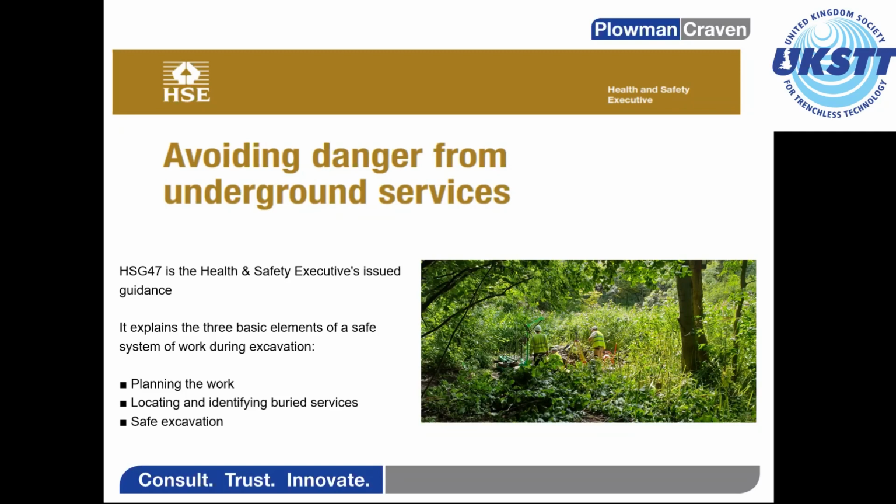This promotes the need to carry out underground utility surveys across all work sites, implementing PAS 128, which is going to improve the level of detail. It deals principally with the risk to health and safety rather than damage to services. However, precautions taken which reduce risks to people's health and safety will generally also reduce the risk of damage to services, which can directly or indirectly pose a risk to people's health and safety. The guidance is aimed at all those involved in commissioning, planning, managing and carrying out work on or near underground services, as well as the owners and operators of said services.